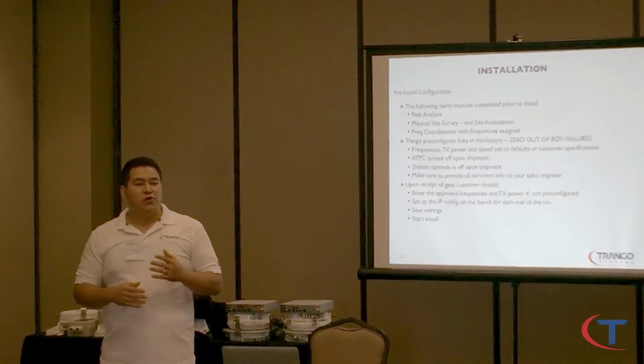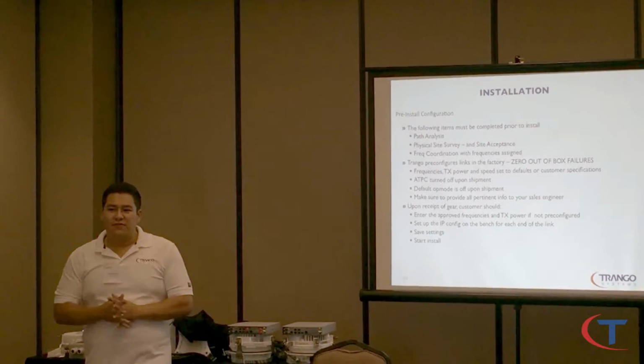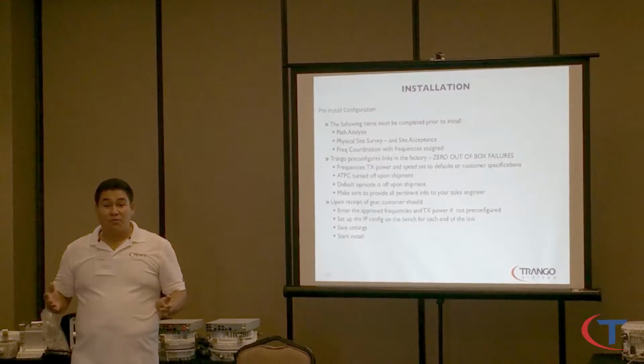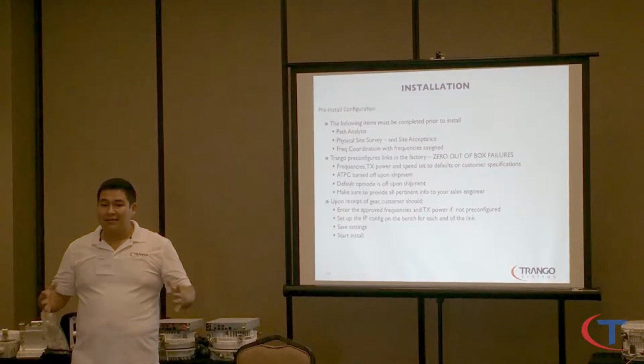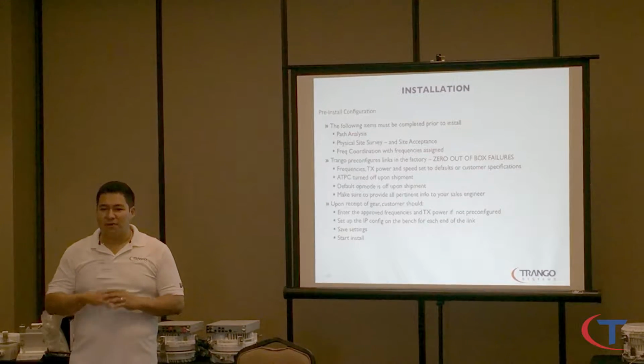Physical site survey is when you're going to lease space on a tower, you want to make sure that it's nice AC power, constant clean power, and grounding is done properly. All the grounding has a common ground on the telecom site. You don't want multiple grounds, that's going to be really bad.